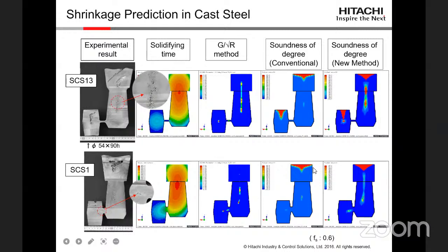You can check, in the bottom images, we have increased the runner size. Then you can check there is large solidification happening again just near the ingate, and this is the solidification happening like temperature distributions.